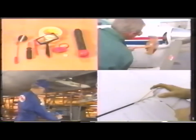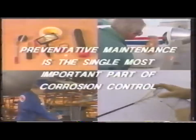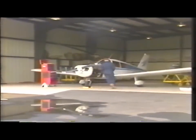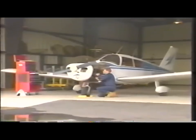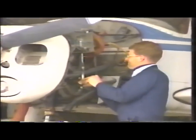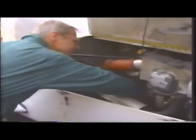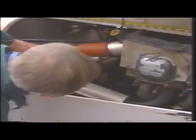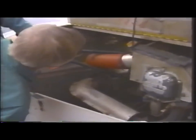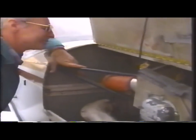If you take one idea with you from this presentation, let it be this. Preventive maintenance is the single most important thing you can do to control the cancer of corrosion on your aircraft. We know that corrosion is not a glamorous subject, and there are other items you must attend to on your aircraft. Despite your busy schedule, corrosion preventive maintenance should remain a top priority. The few minutes you spend inspecting components, washing the aircraft, unclogging drain holes, touching up paint jobs, or applying corrosion preventive compounds will save you hours upon hours of costly component or structural repair.